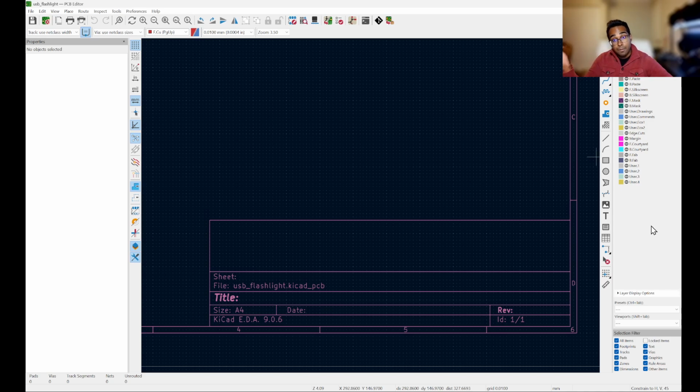Now, what are layers on a PCB? Well, a board like this one has copper not only on the surface, but also on the back. It can even have internal layers where you can have more copper traces routed on the inside. This is equivalent to, on our breadboard, having wires running inside of the breadboard itself.